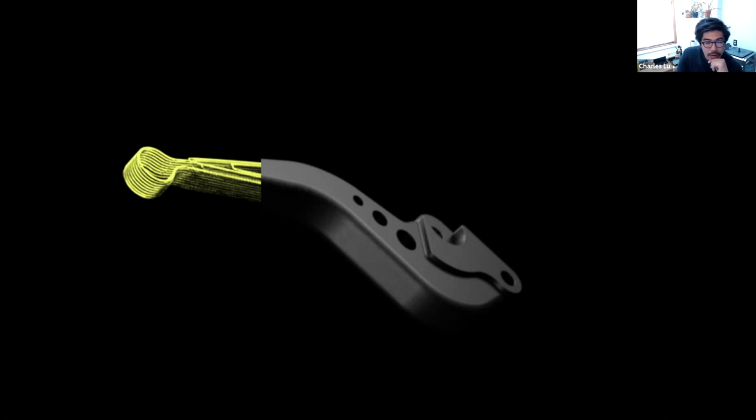Print molds for carbon fiber sheet. Yeah, absolutely. You can definitely do that. You are limited by size, unfortunately, right now. Adhesion issues with that. You would probably have to do a surface treatment. So whatever mold release agent you use for a traditional process, use that. I would recommend smoothing the surface too.